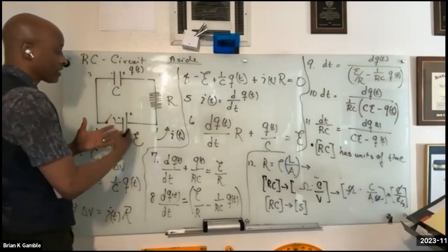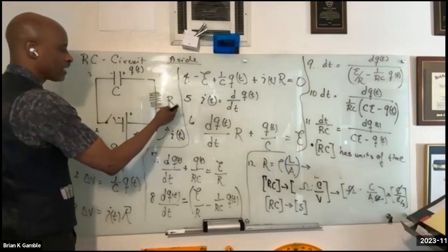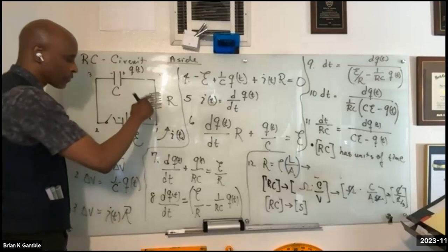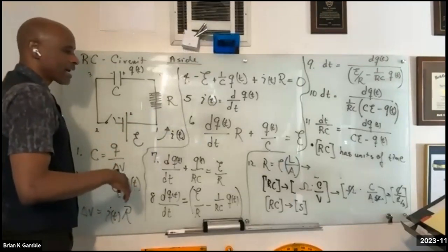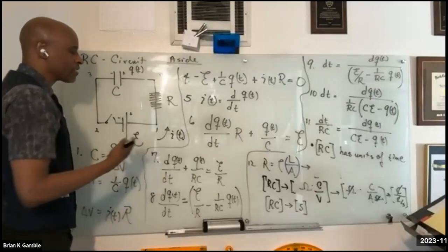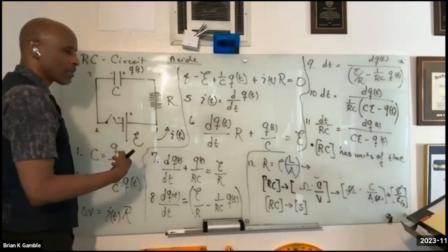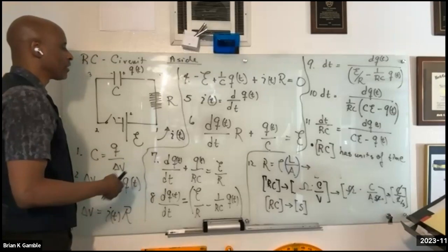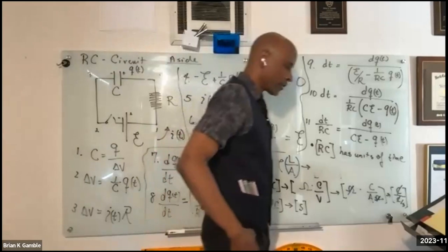circuit and the current is now changing. The reason the current is changing is because energy is being dissipated through joule heating in the resistor, and that's not the case when the resistor isn't there. So it kind of acts like it's taking energy out of the circuit even as the capacitor is charging. So it causes the capacitor to take longer to charge. In the same way, yeah. So that's what we're doing.